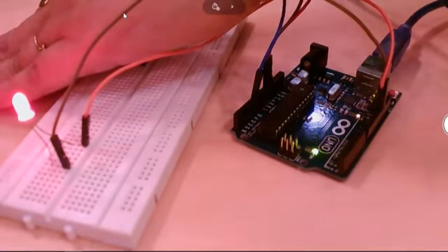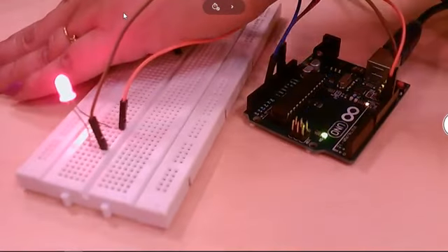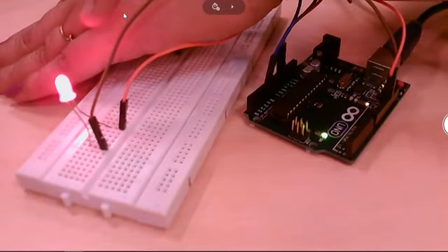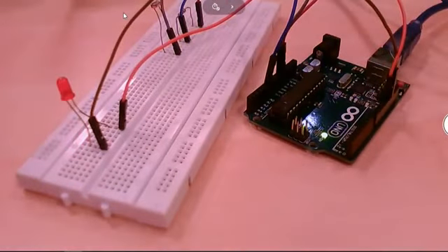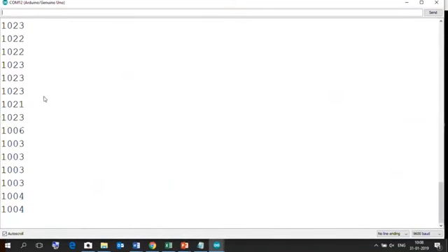Light intensity got changed. Can you see that the LED has turned on here? The moment there is a change in the intensity, those are the values that I can show you here. So sometimes here it crossed 1023. The moment the darkness was there, the value was getting incremented. And that's what I was checking in my code. If it's going beyond some limit, 1021, turn on the LED. And if it's below that value, let's say 1003, which is below 1021, the LED is off.